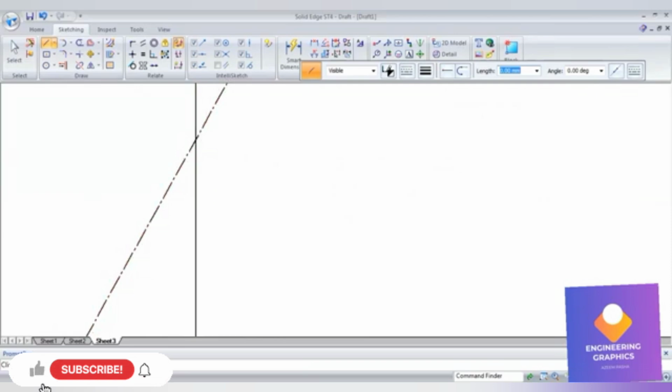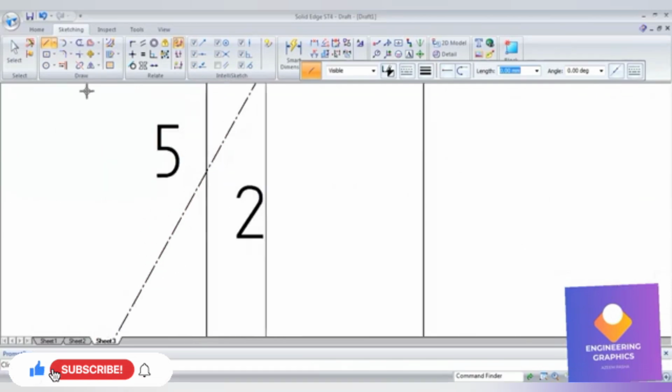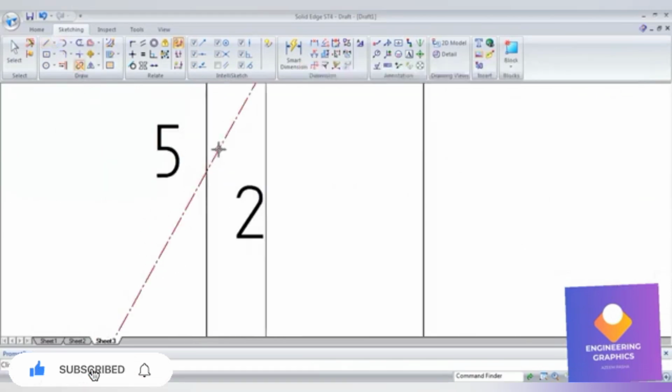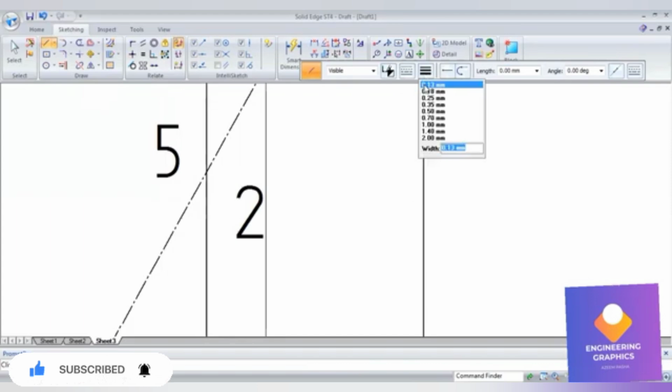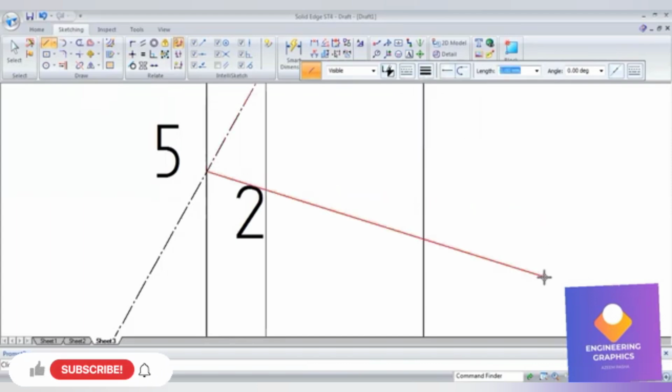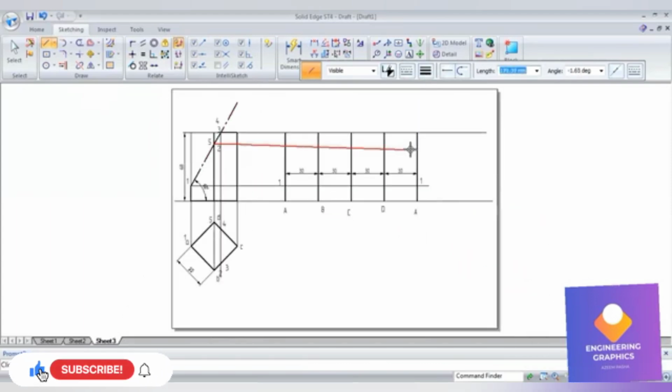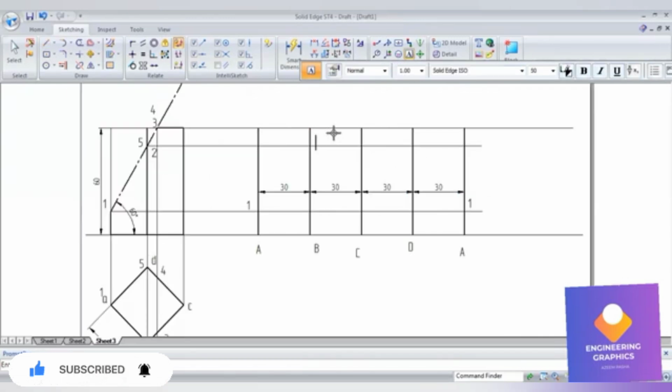Point 2 and 5 we are getting on the same point, but I'm not getting the intersection here, so I can use the split command here, so that I can get the exact point. I'll go to the split command and split it exactly where the section plane is cutting. Okay, so now I'm getting the exact point. From here I'm going to project it horizontally to get the point number 2 and 5 on the B and D. Okay, just by projecting a thin line. So here I'll get point number 2 and point number 5.